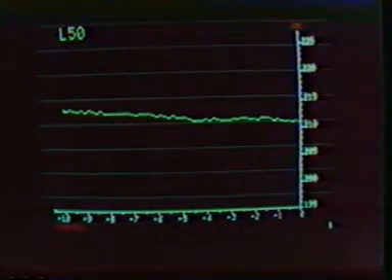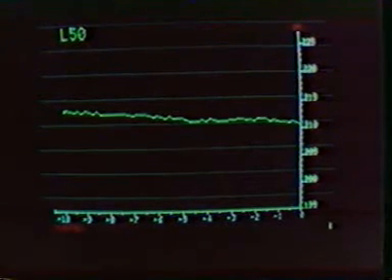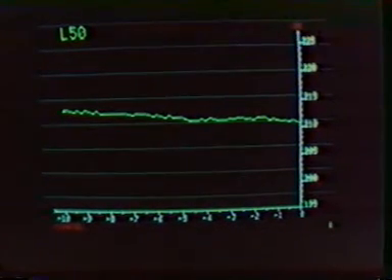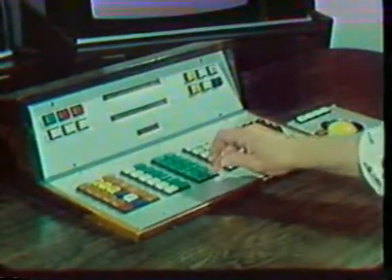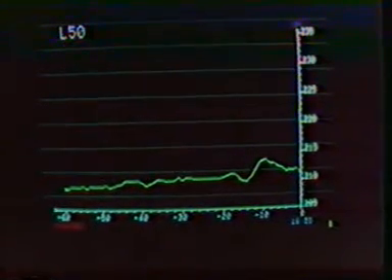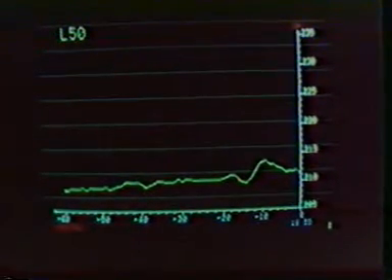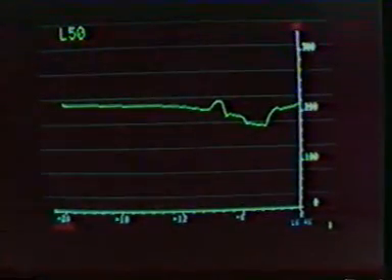For supervision of the process, a number of variables are logged for trend display. The operator can request 10-minute, 1-hour, and 24-hour trends. The 10-minute trend is regularly updated while shown on the screen. The scale along the ordinate axis is automatically adapted to give optimum resolution of the displayed variable.